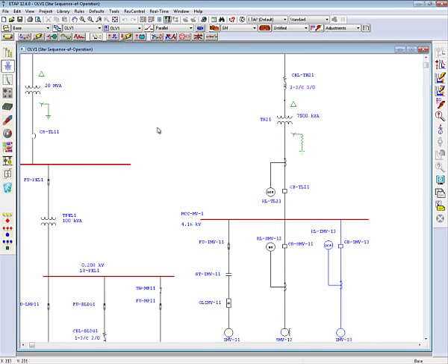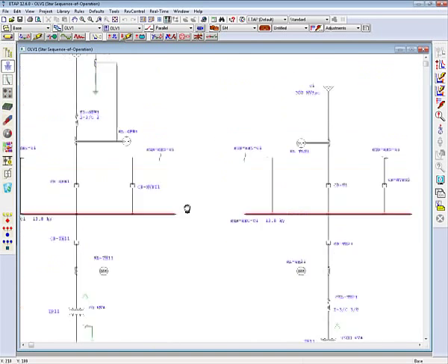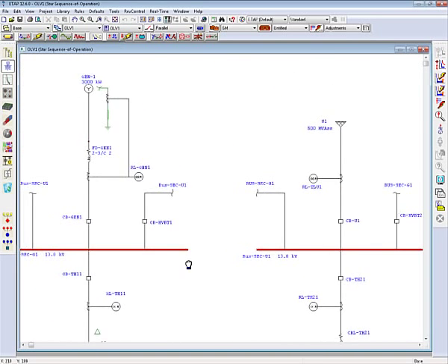If I take you back to the top or upstream of the system, you can see that the generator and utility are connected through a main breaker and some tie breakers between them. Based on the status or service of these main and tie breakers, we can have either one single source of contribution or multiple sources of contribution.